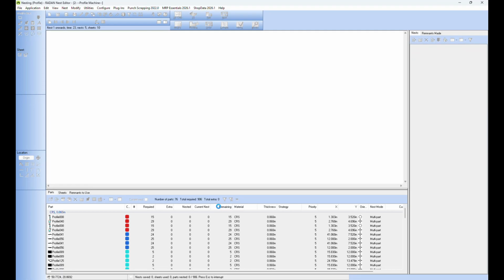So unlike when P1 was 84%, and I'm like, yeah, that's great, lock it in and done, it's probably found something rather similar to that, but it kept it in memory. So as it processes through the entire list of parts, when we get down to 74 and 75 of those tiny parts that we had, perhaps now it can go back, bring out P1 and nest it to it.